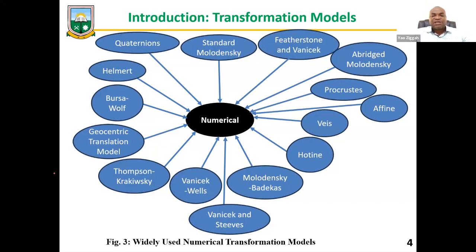So they prefer using the Molodensky-Badekas for smaller areas as compared to the Bursa-Wolf. Now the Helmert, at a point, they realize that it's more or less like an iterative system. Then the Bursa-Wolf gives us a closed form solution of the Helmert. So all these methods were proposed based on certain computational deficiencies that have been shown in other methods. So the idea is to improve it.